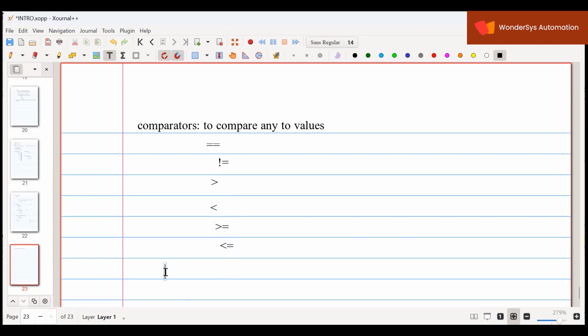So here in this comparator, we have a particular command. If you are using equal to or not equal to, we'll have that particular command. It varies from one to another. Then I can do a direct value to value comparison. If I mention hash, it is direct values. Otherwise, the other format is an address, as we used in our converters.